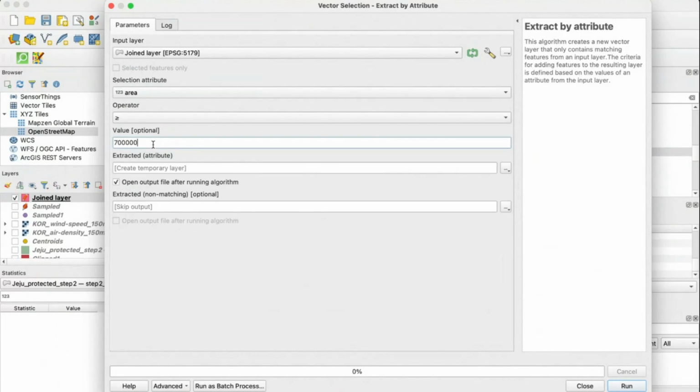But unfortunately, using QGIS, it is very difficult to say the wind turbine is going to be at the center and make sure there are no houses or anything around within certain meters of this point. Calculating those kinds of things is a bit more complicated. Of course, you can do it using buffer and some more complicated functions.